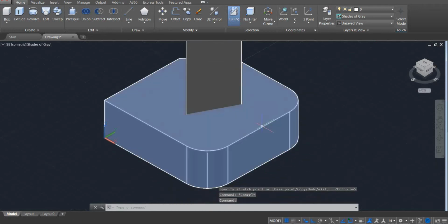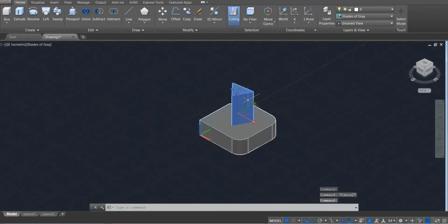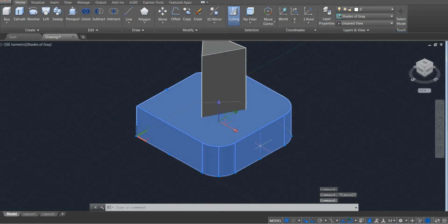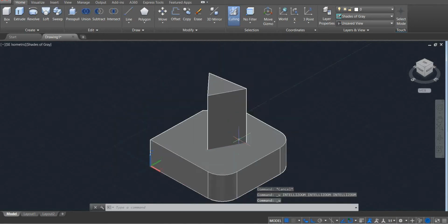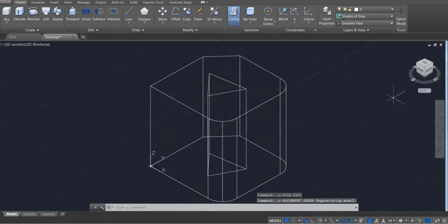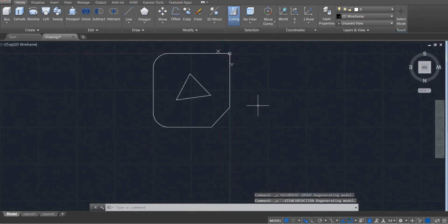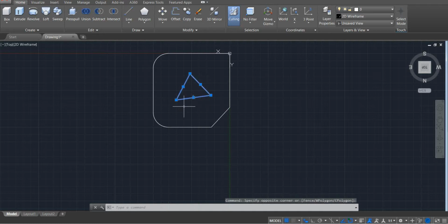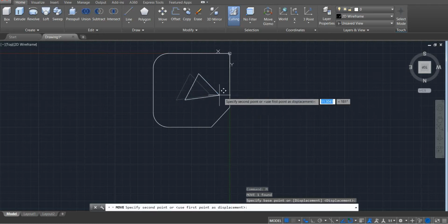So as you can see, we do have one object and there is another object. What I did here, I edited this solid, I shortened this solid. This editing thing, we're gonna discuss later, okay? But the key idea of the extrude command is that if we have multiple closed loops that are joined and we extrude them, we're gonna end up with multiple solid objects.